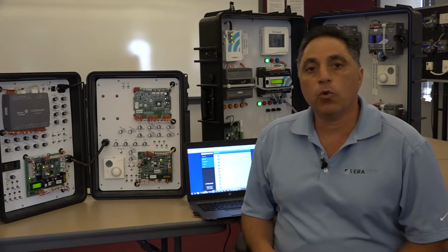It creates an experience for the mechanical contractor or the service provider. FDD can provide you, with a combination of smart equipment and Verisys, information ahead of time when you have a true problem from a refrigeration perspective of the system. There are two different types of FDD within our rooftop. One has to do with the economizer. But the main side of the FDD that I want to talk about today has to do with our refrigeration circuits.